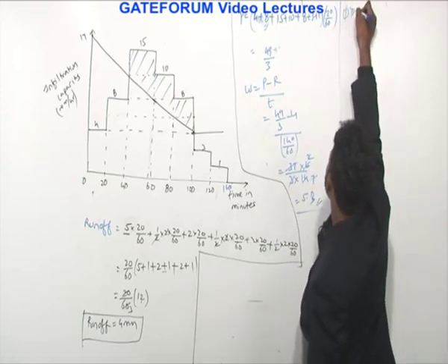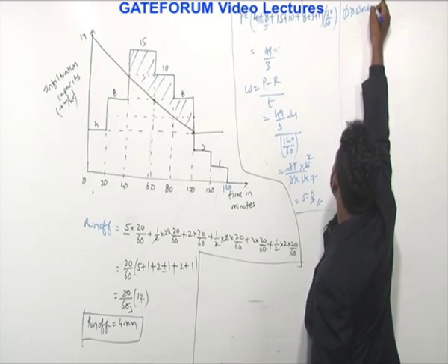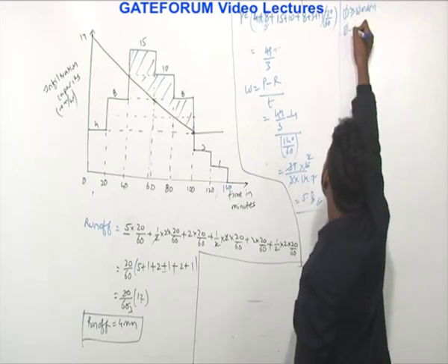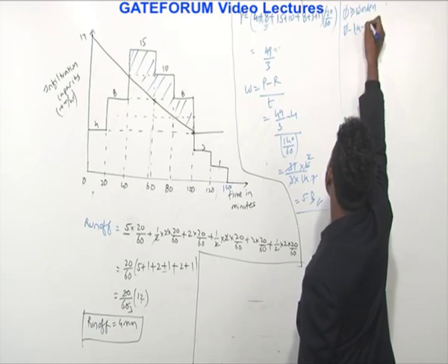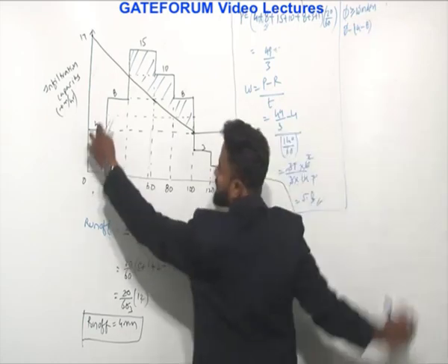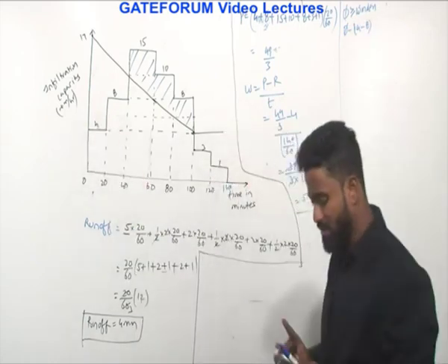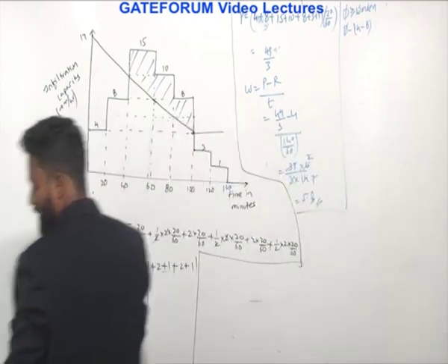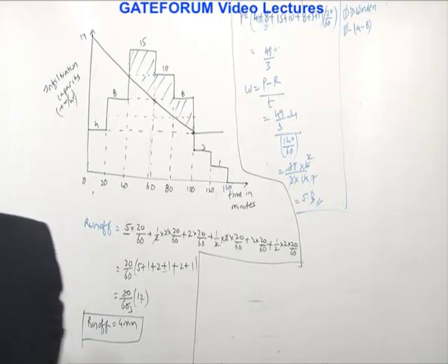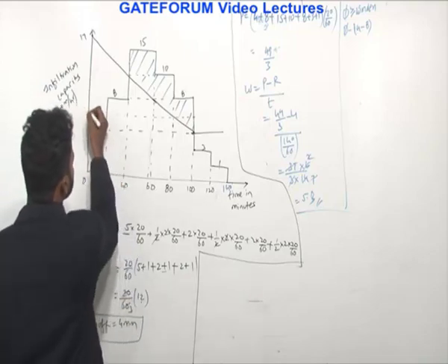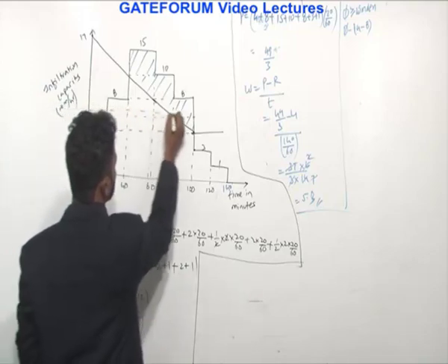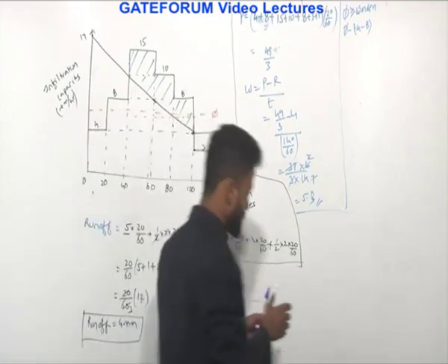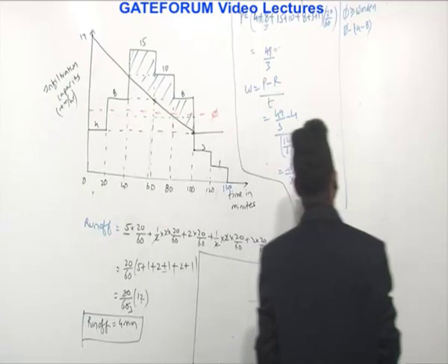Phi is greater than or equal to W index. You can start your trials from 5.3 or assume phi is in the range of 4 to 8. That means phi index is in this range. If phi index is in that range, I'll take some value of phi index. Let us say this is phi.